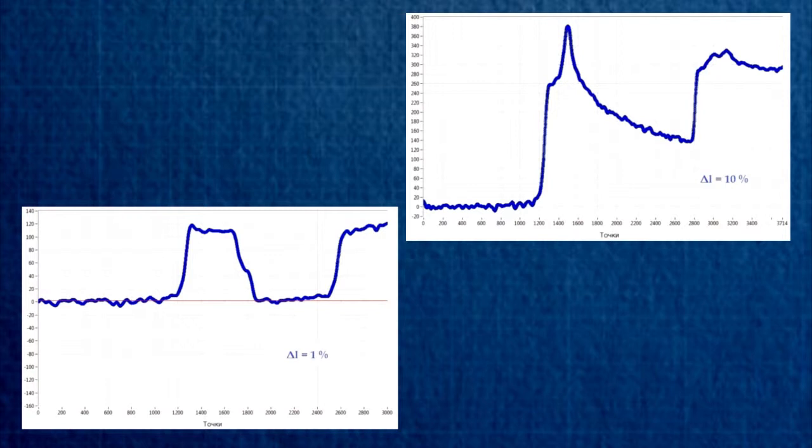Thus, the OGK-01 installation enables assessment of the condition of the contact zone of the cement stone formed in thermobaric conditions. To demonstrate the results of the study, we have prepared two materials with linear extension of 1% and 10%. The samples are mixed and dispensed into molds to form the cement paste, with further placement into an oven where they are stored for 24 hours. Using the threaded connection, the samples are screwed to the OGK device and are ready for testing.